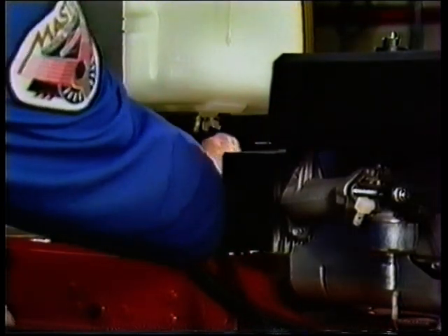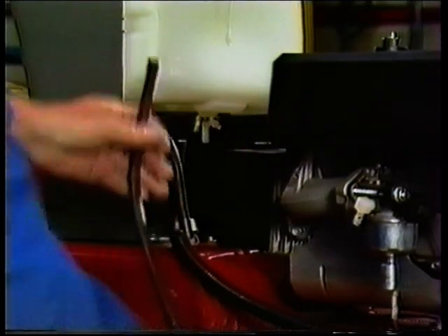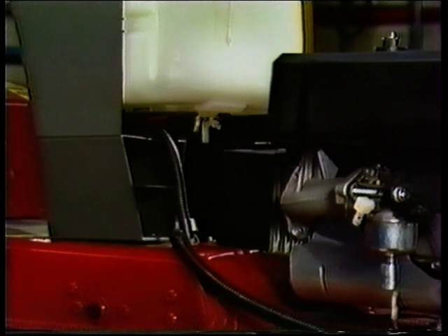Once the tank is okay, remove all fuel lines and filters and replace them with new parts which meet Briggs & Stratton specs. Disassemble the carburetor. Then, thoroughly remove and check every removable internal part. Sometimes dirt can be very hard to find.